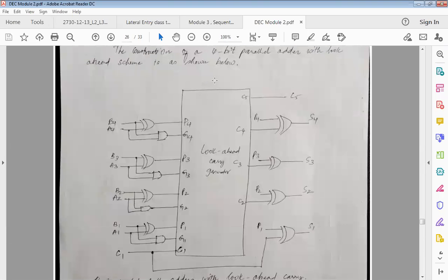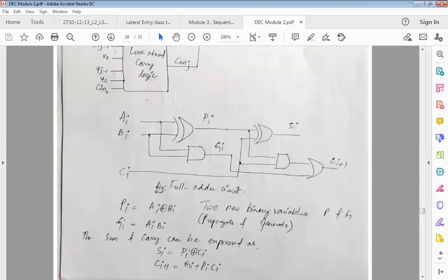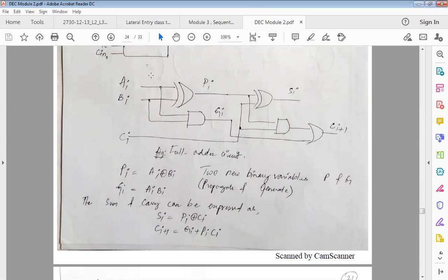So this is a 4-bit parallel adder, and we have the generator in between. So I'll be giving the inputs A, B, and we'll be getting the propagate and generate values. From this, we actually pass on to the next stage. So remember I told you, this is the first stage. If we just logically draw a line here, this is the first stage, which is having Pi, Gi values. And when these values are passed to the next level of gates, we call it the second stage, right? So in the second stage, in between, we are actually adding the carry look ahead logic, right?